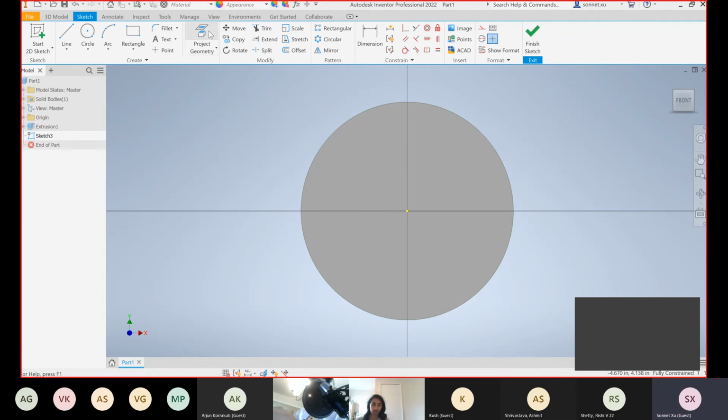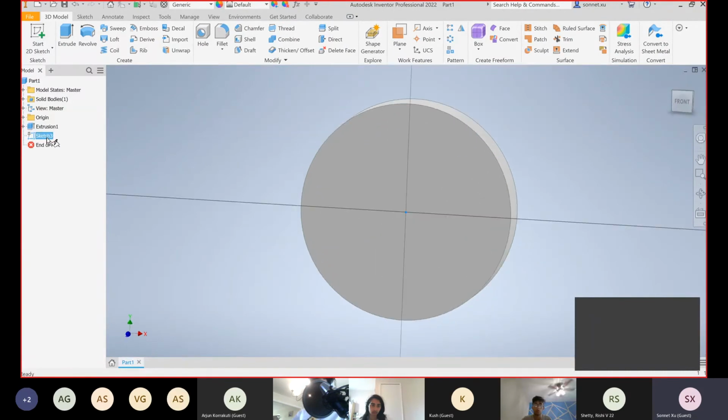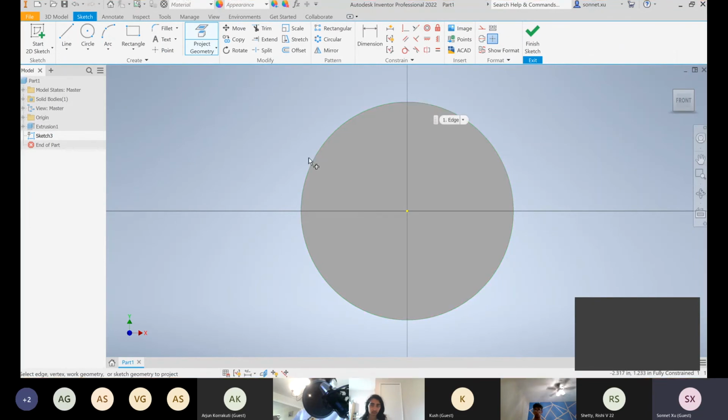Okay, I didn't realize it was muted. So what we're going to do next is use a tool called Project Geometry. Just to show you that again, you have this, and then you click Start 2D Sketch, click on this face, and start another sketch. We can do this Project Geometry. What Project Geometry does is it allows us to take in the geometry of the previous sketch.